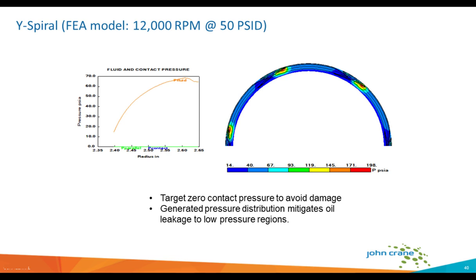So by looking at this, the seal face equilibrium is established between our force balance between hydrodynamic and hydrostatic opening and closing forces. And then we've got high pressure spikes that show that pressure generation at the peaks with this low DP application.